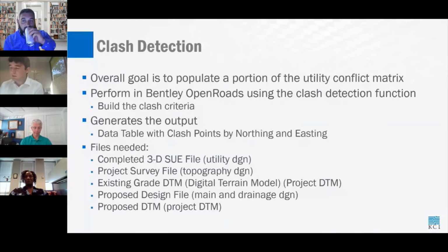And the goal of going through the exercises of creating metadata for utility line work, which is basically data about data, and adding utility structures into 3D to a utility drawing, is to create a utility file that not only visually represents what we are looking at with regard to underground and overhead utilities, but also is practical in taking the next steps to determining where there are utility conflicts.